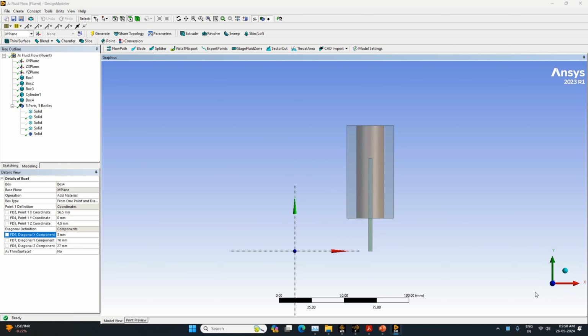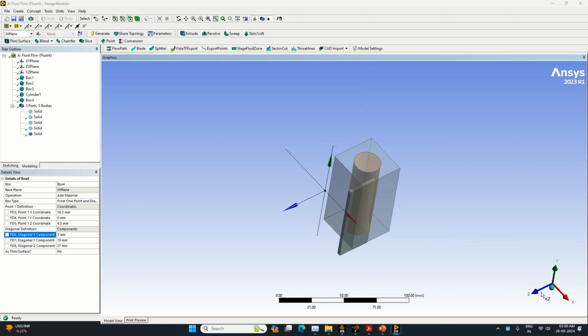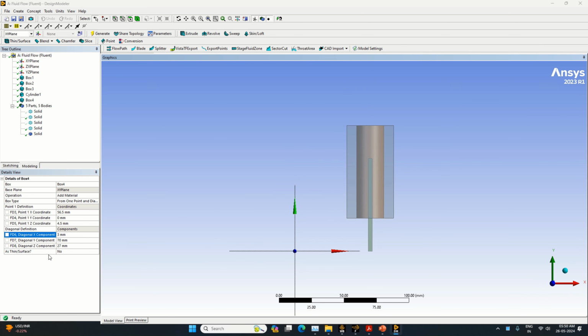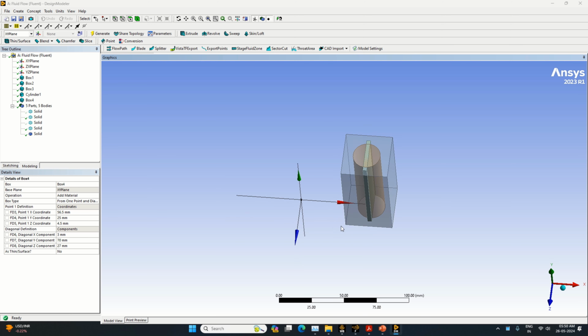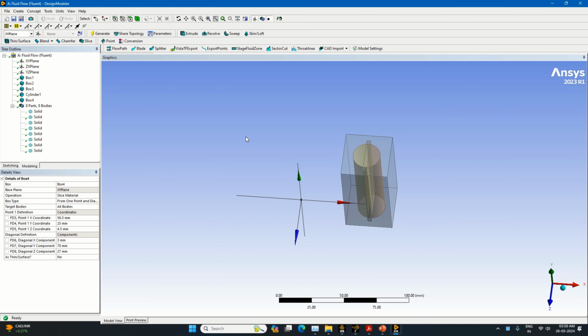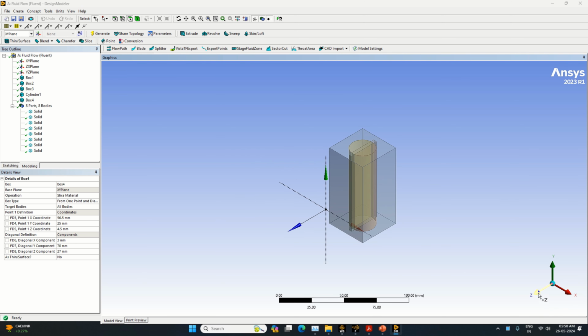So accordingly we have to shift this further. I will shift this further in y direction now. So let's go in the y direction, as per the dimension we have. I will go by 25. So make it above here. So I will make it slice material over here and generate. So this is how the first type of fin I have generated, with a thickness of 3 mm.